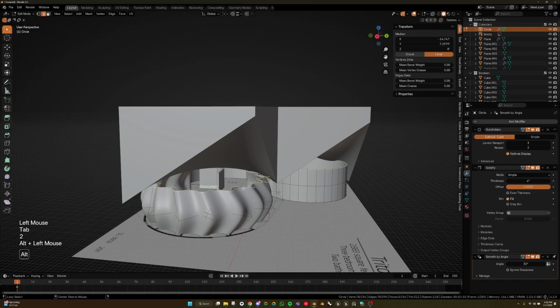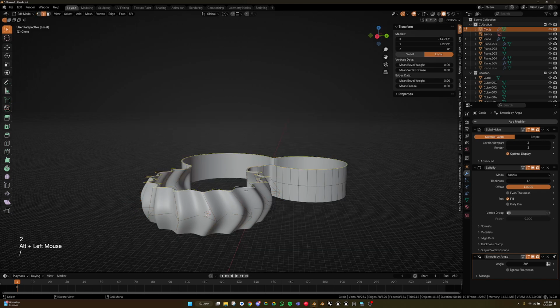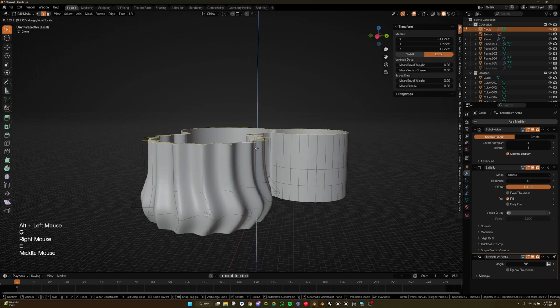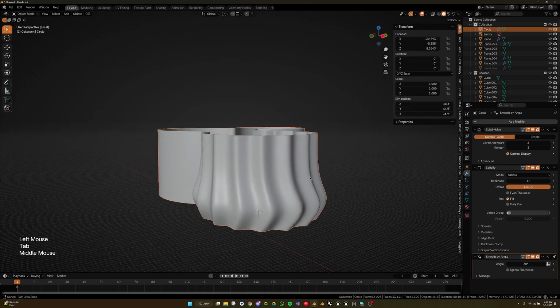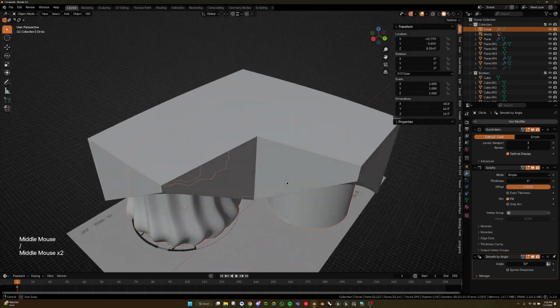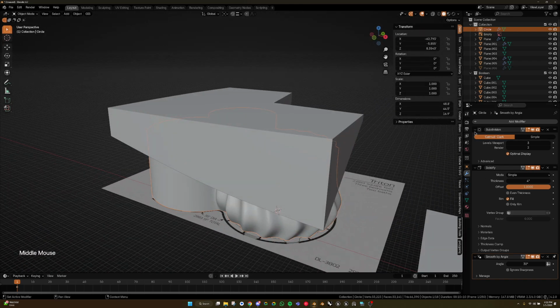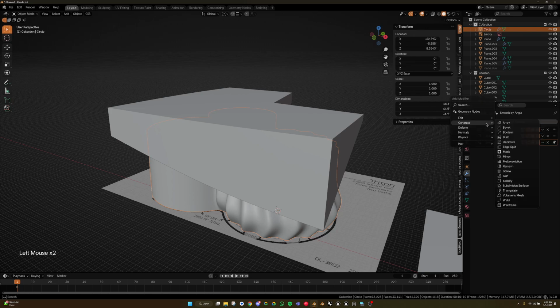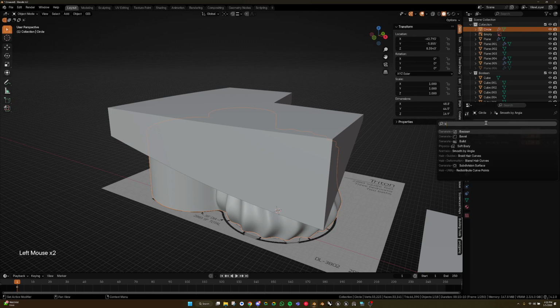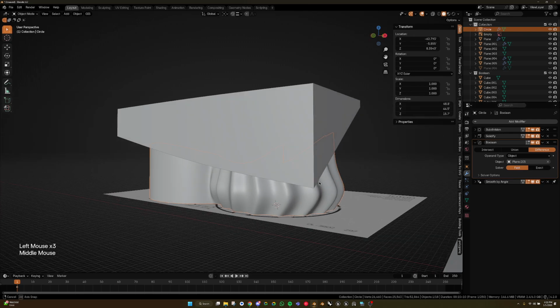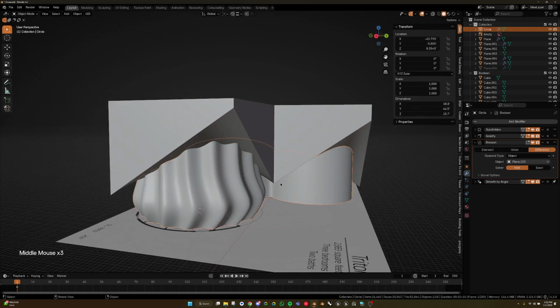So we'll just select the loop cut by pressing Alt-click. So that selects all of these faces, and then you could just extrude it up into the structure, just like that. And let's see, it's all in, it looks like. Yep. Then we can collapse all of these and do a Boolean, right? Boolean into this. Now we might want to do fast. Yeah, fast will work, thankfully.